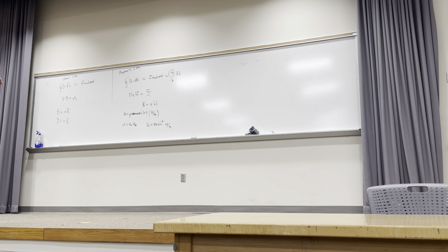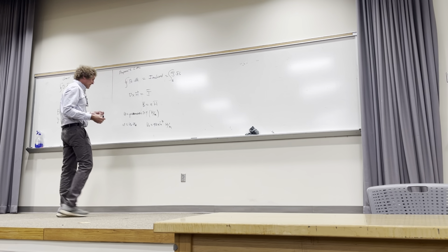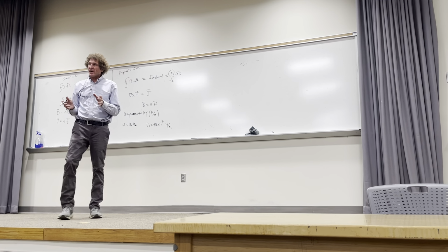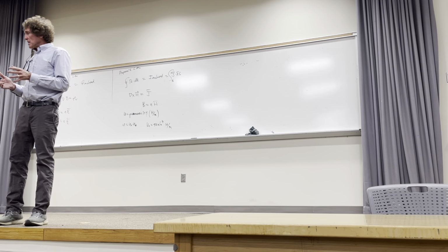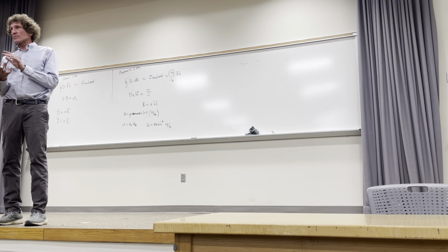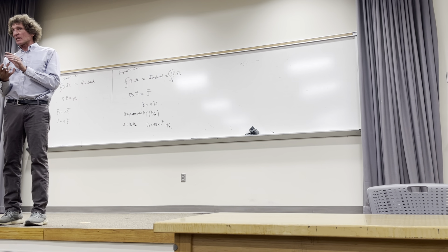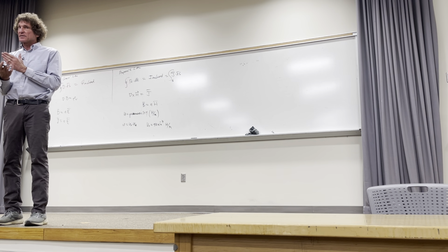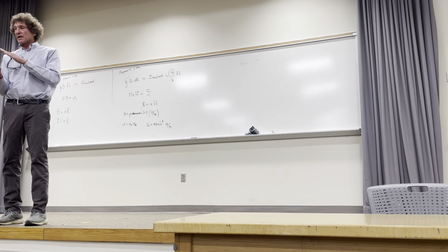Now, I'm going to tell you this much. When you talk about values of mu, before I go down this road too far, here's what's really important: transformers. You all know what transformers are, right? Usually low frequency transformers are iron. They actually are laminated iron. They take iron, they cut it into very thin slices, and then they coat those with a shellac or some insulator, and they stack them.